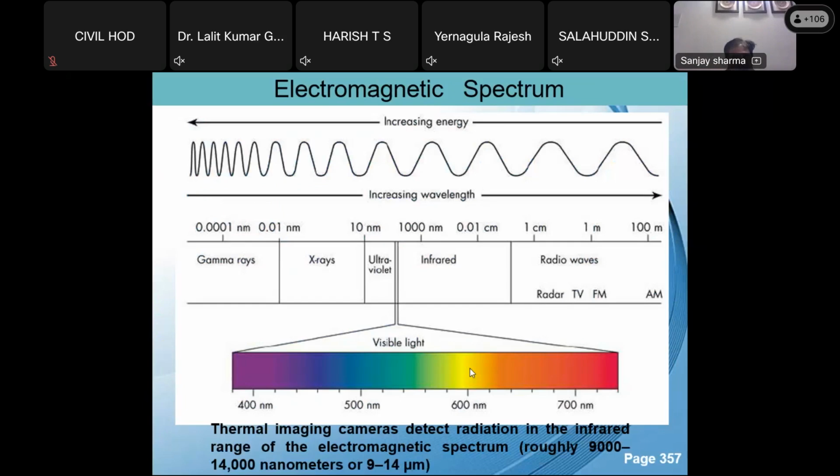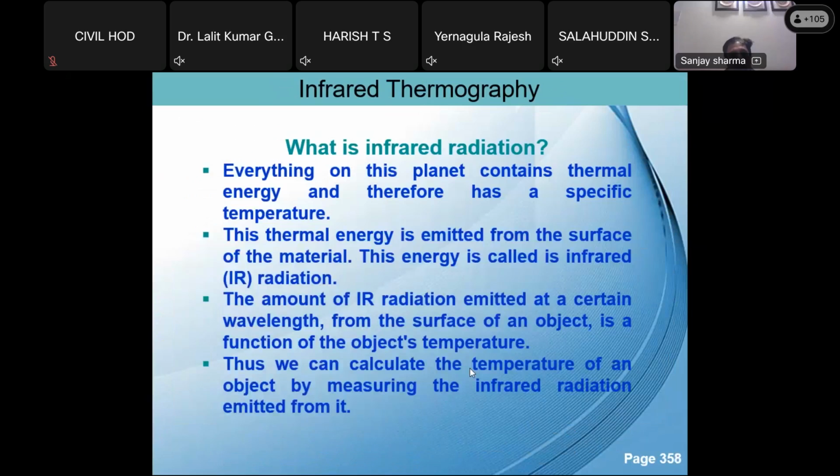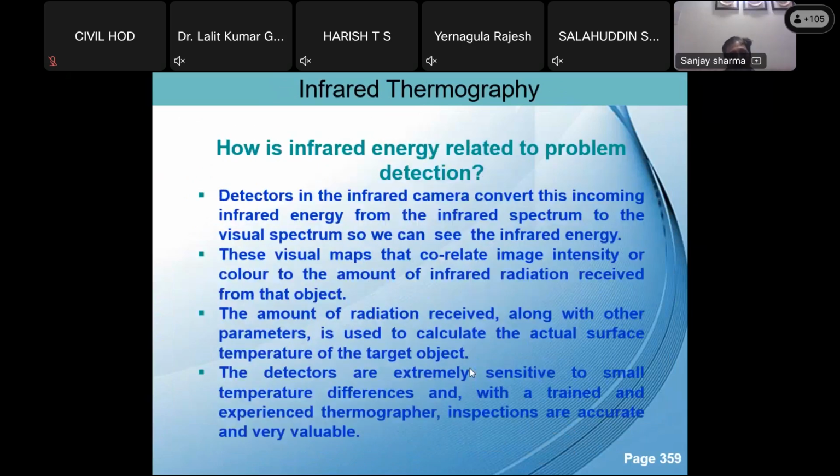What we measured using this camera is temperature. This thermal camera gives you the temperature. High temperature means okay, but low temperature means there is moisture. So we identified those areas where the moisture was, and then identified the members which require replacement, using this infrared thermal camera.